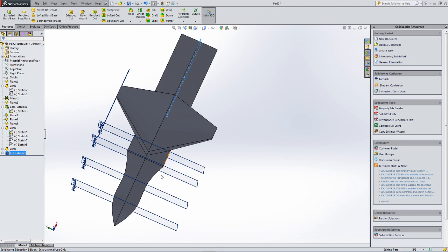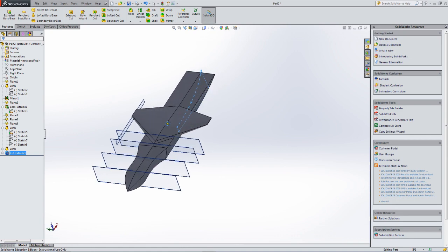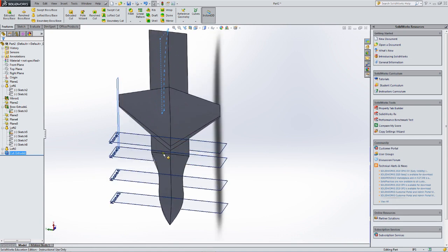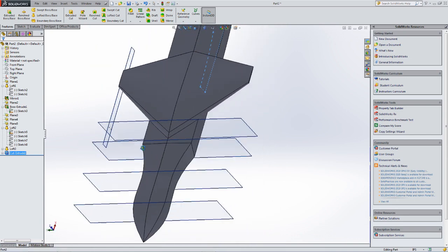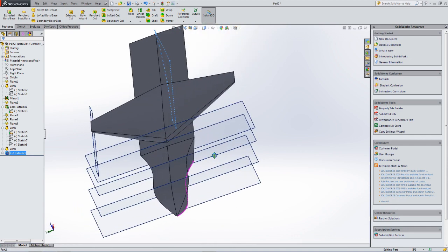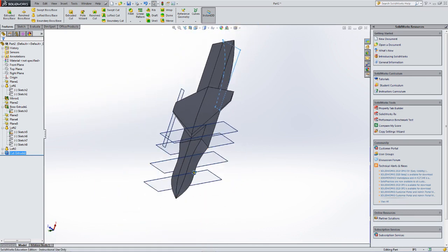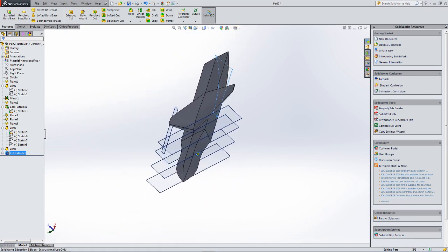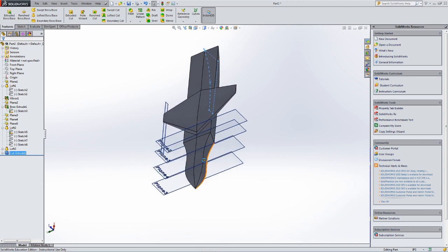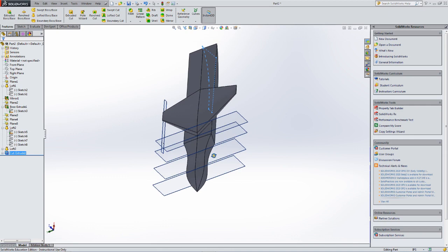So what I'm going to do for this model is define strakes as the top of the inlet. Then if we wanted to, using the methods we've already seen, we could draw the rest of the inlet. So I'm going to draw those strakes as an extrusion, okay?